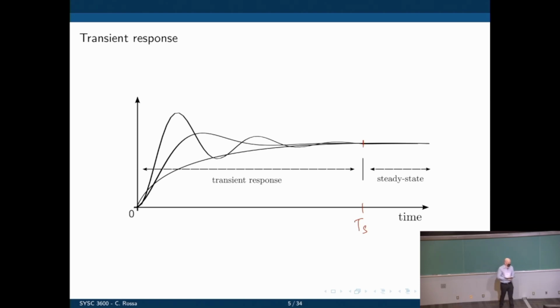What else can we quantify here? We could, for example, look at how much the system will overshoot before it settles at its final value in a steady state. What is that bump there? How much is it? What influences that thing? It's something you can quantify as well.